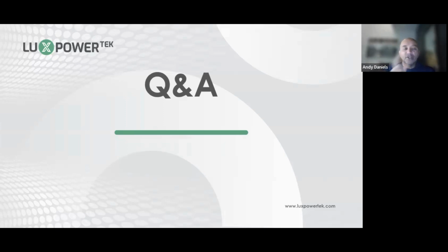You populate everything. Let's just say, for argument's sake, we're building a parallel station with 4 inverters. We take the first dongle, and we use dongle number 1 to register the station. Then we go into the user portal, we log in, and as an installer, you can look for that station. You find it, click on the management, and go to add dongle. Then you will add dongle 2, 3, and 4.